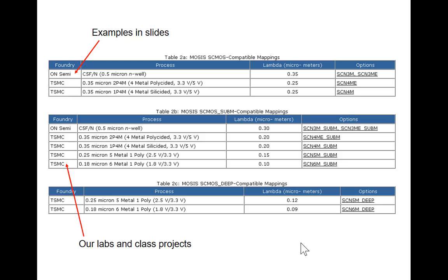But some other foundries will just spell out how many polys. Maybe you have a 2P, that stands for 2 poly. And if you do an HP, then there's a high resistance poly. That option is there. So it has different designations, and different companies follow different ones. But you don't need to memorize these. You just need to look at what they mean.